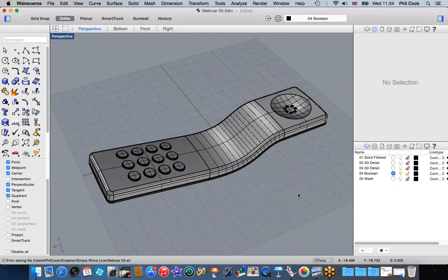Okay, thanks. One other thing, just regarding normals. I think as part of your process this morning, you were changing the direction of normals. Yes. There's a question around that: is that something you have to be aware of often and look at as part of a modeling process, from minute to minute, or how important is that aspect of control? No. If you have, for example, in normal modeling, a couple of surfaces with different normal directions and you join them together, Rhino just takes care of the normal direction and unifies that. There are only a few times where this becomes important, and one of the times is using Boolean operations on surfaces.